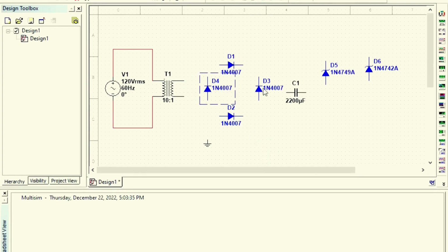Now we need to make a rectifier using 4 diodes of 1N4007. So both opposite diodes have the same position, now connecting them all to make a rectifier. Each diode must be placed in the right position in order to get the desired output. If even one of them is connected in the wrong position, the circuit behaves abnormally. This rectifier portion converts AC supply into DC supply.